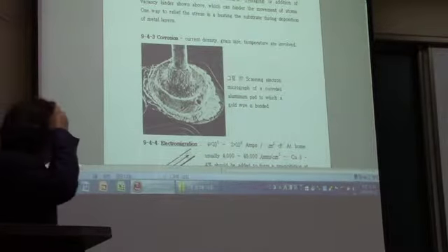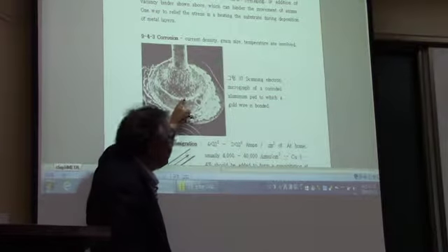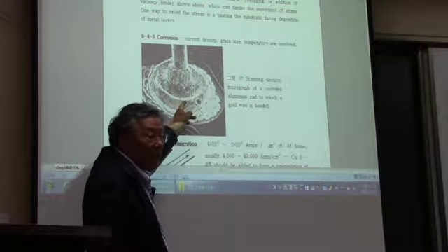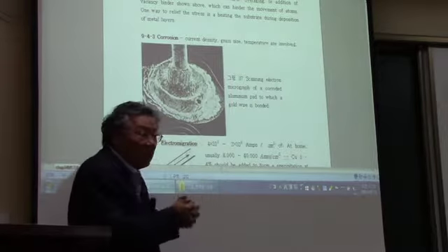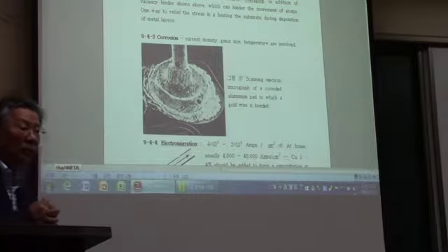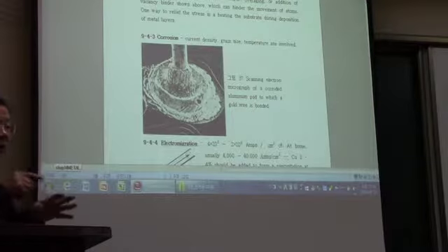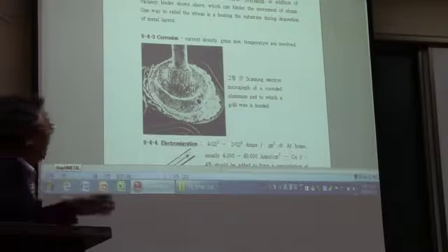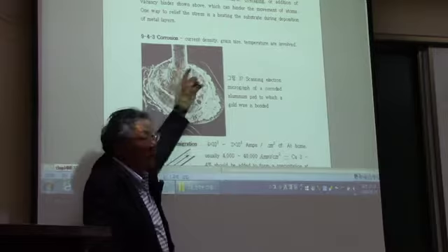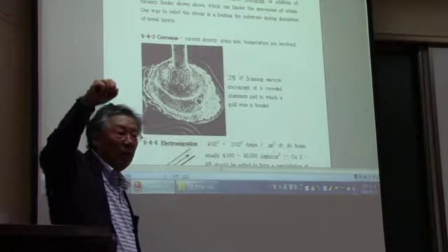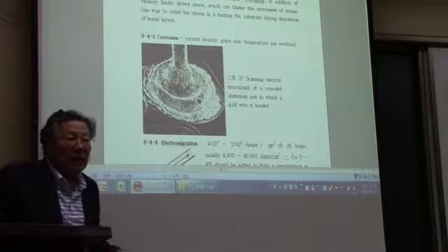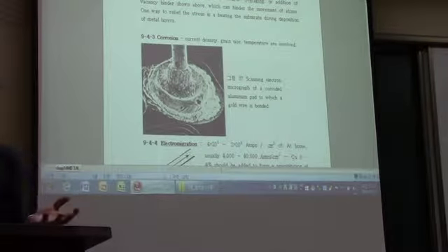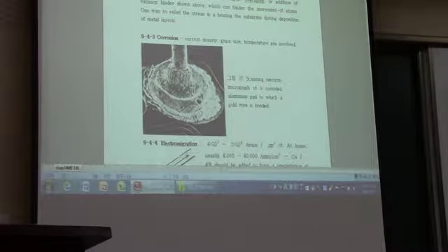And then if this aluminum is corroded, and aluminum is corroded only by chlorine with moisture, then this gold line is going to be detached from the pad, so that it's not going to work anymore. Now, this thing is important because it's related to the guarantee period of the product.